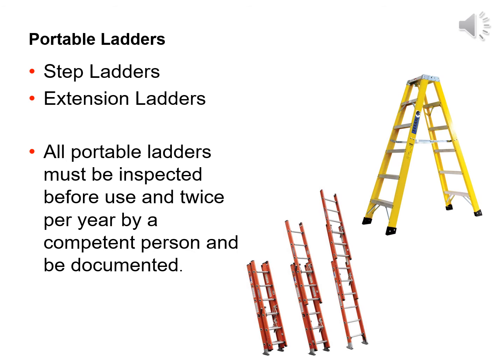All portable ladders must be inspected before use by the user and then formally inspected twice per year by a competent person. The formal biannual inspections are documented in the records kept in the safety department.